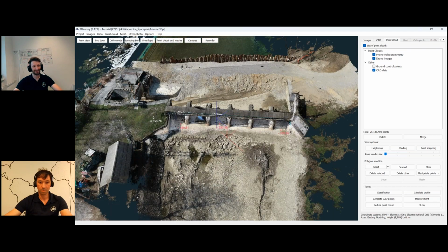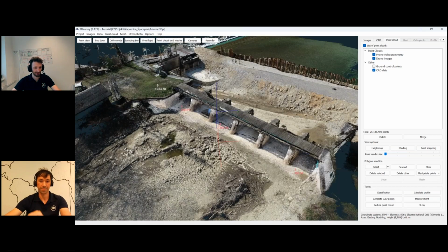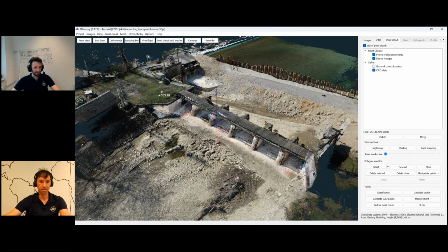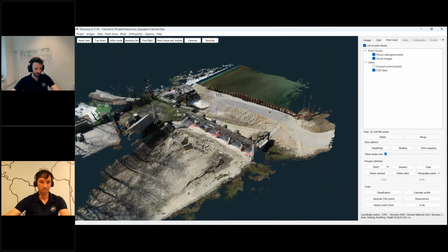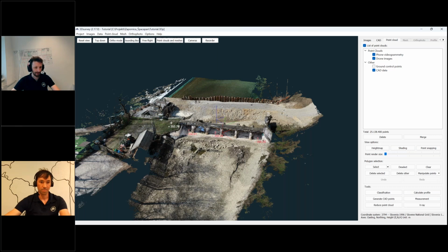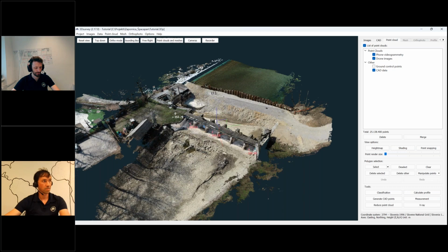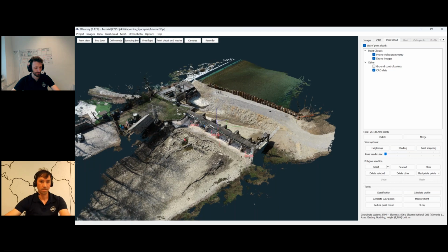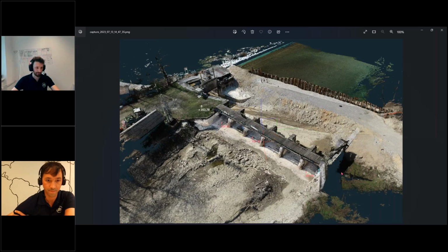There's also one minor update that's also quite nice. That comes with the 2.17 version, and I will present it also on this data set. If you remember the last time we had a webinar, we presented the snapshot option. If you press C, the program will create a snapshot of your rendered area, which is exported into PNG, and you can share it right away. It's the fastest way to share your work in 3Dsurvey.